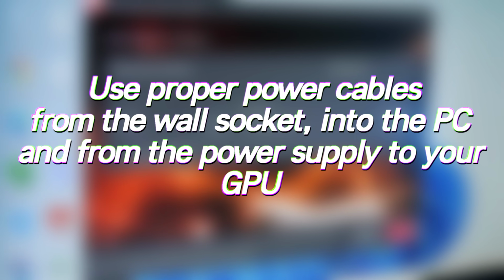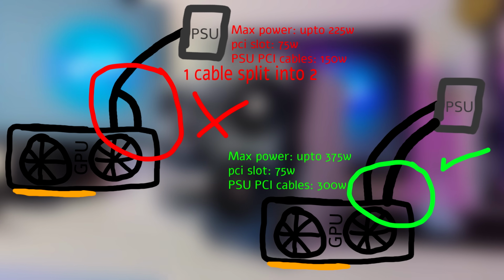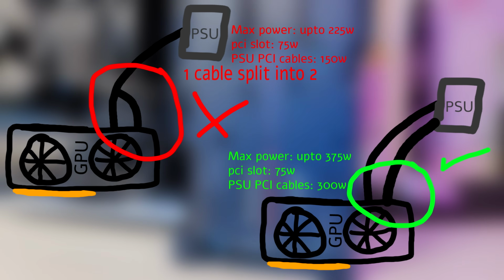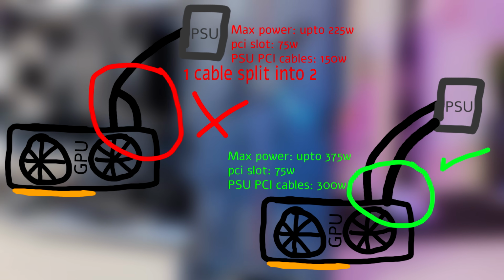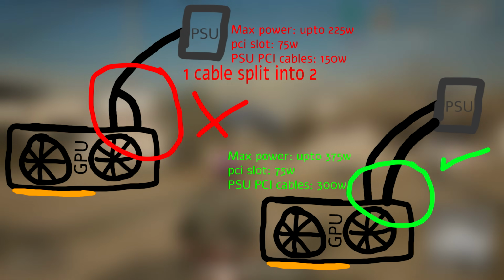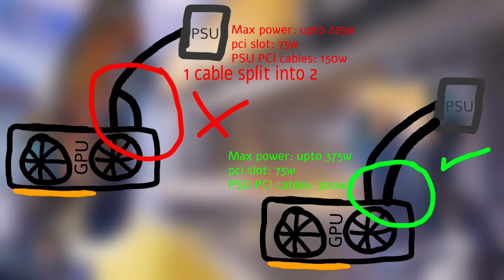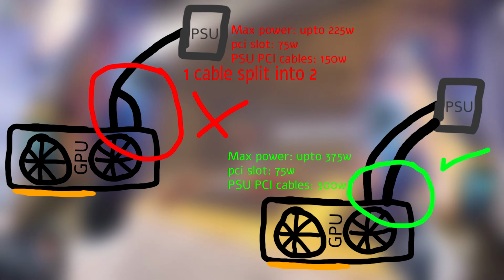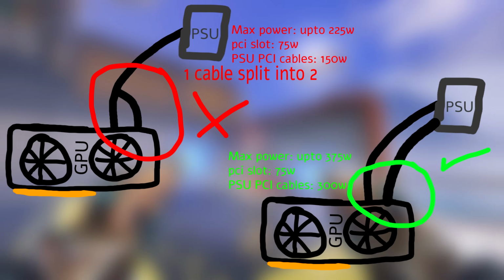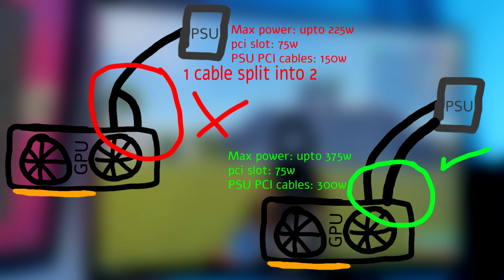First of all, regardless of how high or low end your graphics card is, you want to make sure that you are using correct power cables and are not daisy chaining power cables. If you're not sure what I mean by this, you don't want to be using an 8-pin power cable that has another 8-pin power cable attached to this, meaning that you have both power cables going into your GPU from one single cable. One single set of PCI power cables are only able to deliver roughly between 150 and 175 watts. If your GPU power goes above this and you are not using two individual sets of cables, you're going to be power starving your GPU and it's either going to crash or downclock. There is no way around this. You need to be making sure that you are using the correct amount of individual power cables.